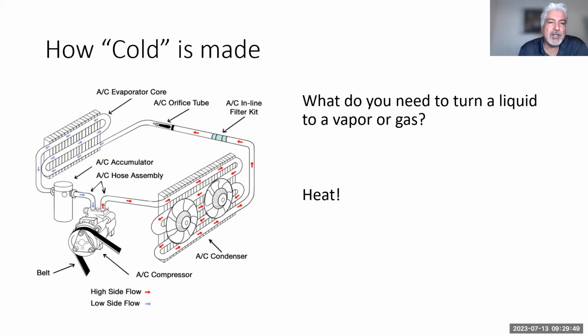So what's the best security device? Like I said, some type of inline filter, especially if it's had that happen. I am not going to do a compressor if I knew that orifice tube or that system was contaminated. So definitely protect it by putting some type of filter or screen on it, either the screen on the inlet on the manifold assembly of the compressor or on the lines themselves. So definitely can do that.